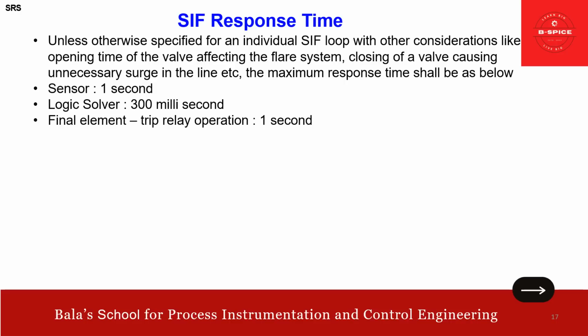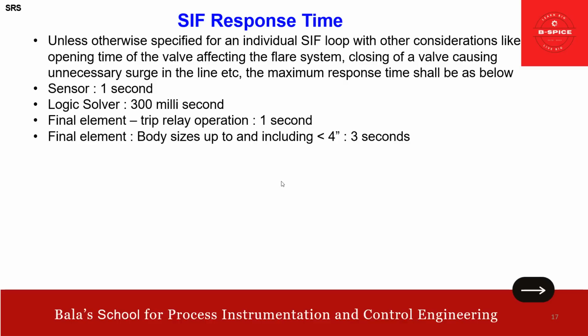I actually explained earlier in the previous slide, like 4 minutes and all. That was just put up for example only. So maybe you can consider 4 seconds for the process time. The SIF response time is 50% of the process time. So here it is 1 second, 300 milliseconds, and final element 1 second.